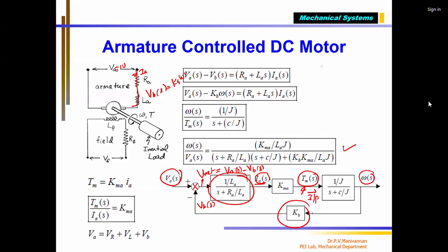So when you give the feedback, this is my output, the motor shaft. Torque also develops on the shaft. I can say that TS is called the shaft torque. This Tm is called the motor torque. Note down, that is the motor developed torque. It will always be greater than the motor shaft torque. Why? Because of friction, inertia, and all these things consume some amount.